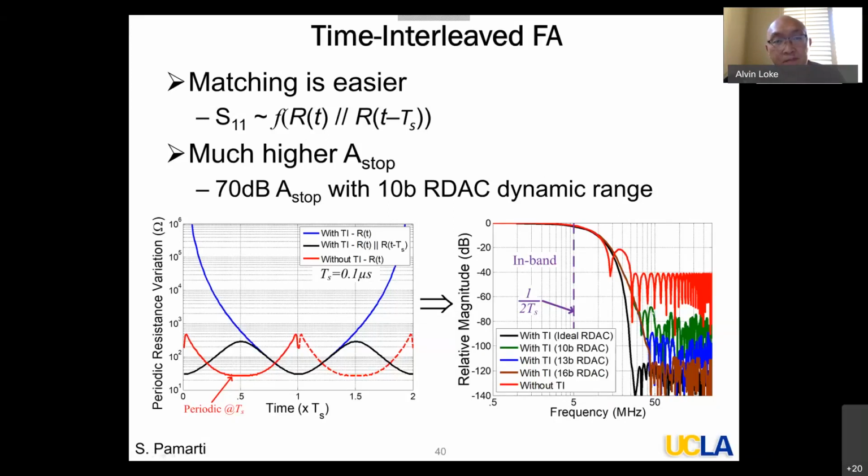Yeah, so it is fairly insensitive to the resistor errors. Like I said, this green curve is a 10-bit quantized version, which means that any error less than the 10-bit value, we don't care. When we do this quantization, we try different versions. Sometimes we put in random errors in the various resistance values. As long as the RMS value is below the 10-bit level, then we are okay.